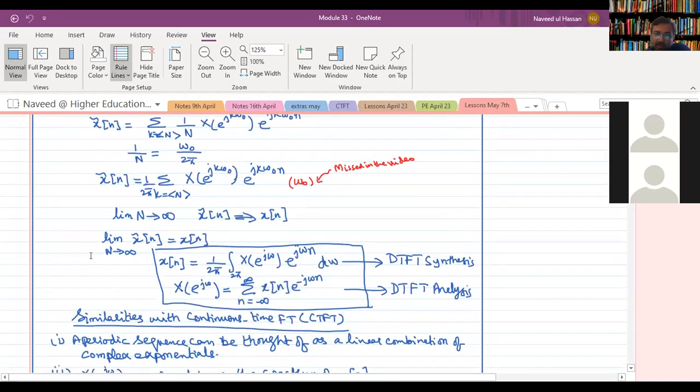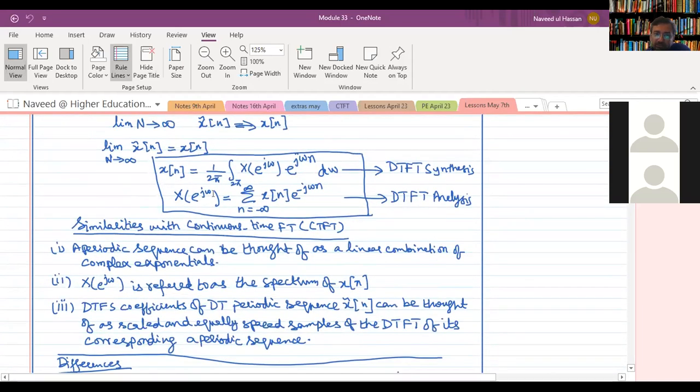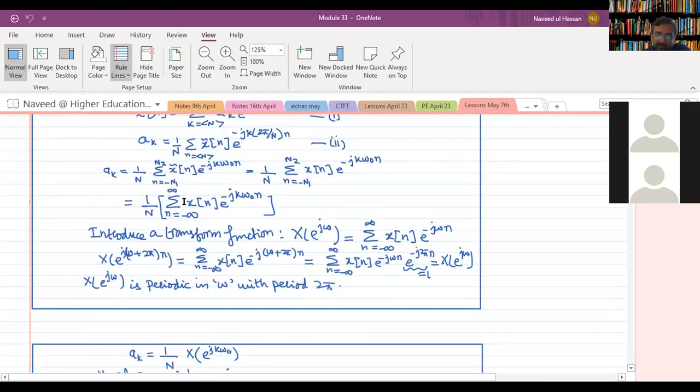तो अगर हमें discrete time Fourier transform किसी function का पता हो, किसी सीक्वेंस का पता हो और उससे हम एक पीरियोडिक सीक्वेंस बना लें, then using that transform we can find the discrete time Fourier series coefficients of the periodic sequence. ठीक है, so it comes from here.